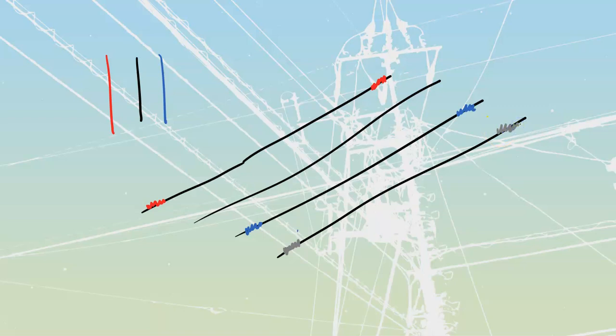I know it's gray over here, but it's the closest I got to white for markers. You're going to do this inside of all of your cables. Usually you identify them before you pull them in. However, in some cases, people will pull them in and then meter them out later on to figure out which phase is which at the other end.